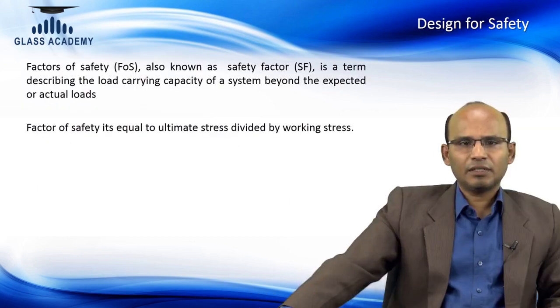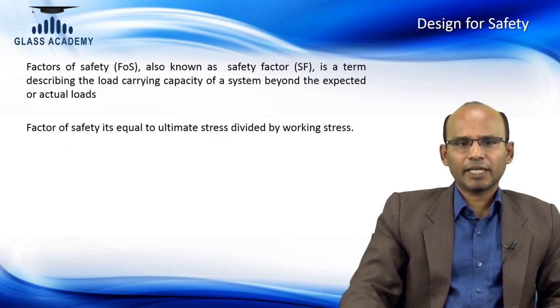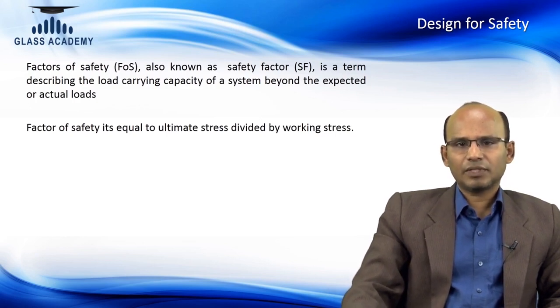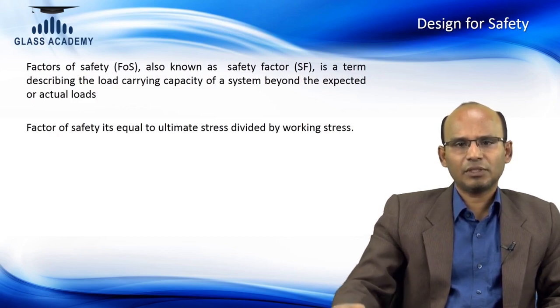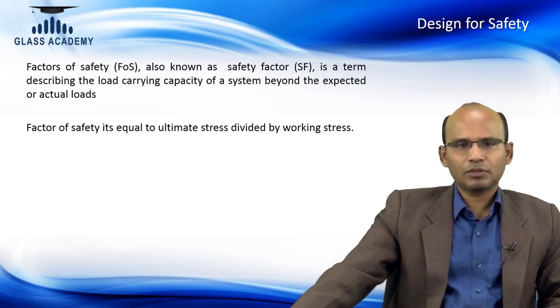Factor of safety, as typical to any other steel design or concrete design, is applicable to facade elements, being glass, cladding panels, or framing elements such as bracket details. The safety factor for framing elements is generally 1.5 times, and for glass elements the safety factor is much higher, like 3 or sometimes 5. It depends on the glass types or which standards are being used.